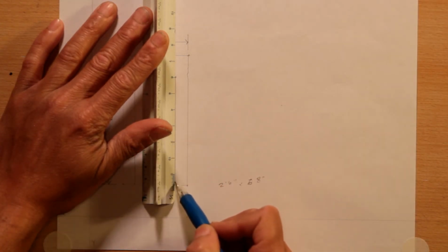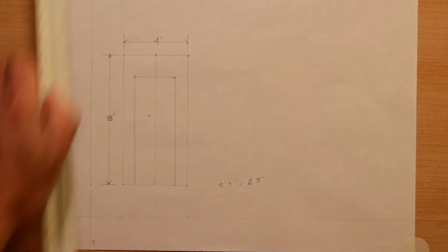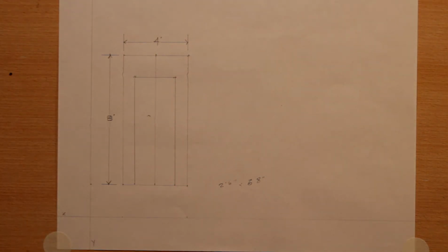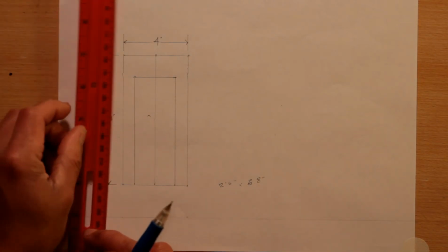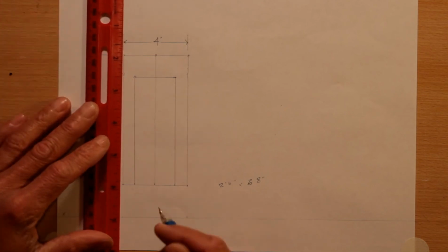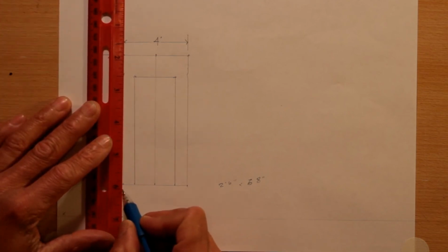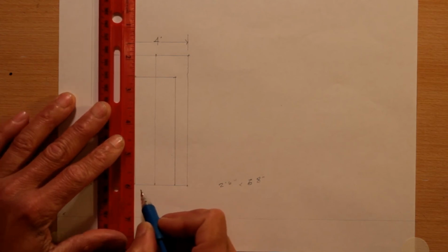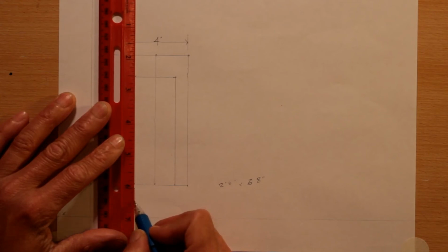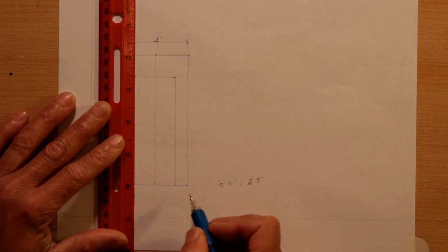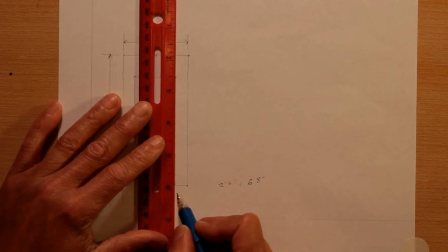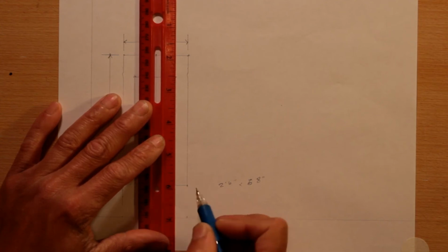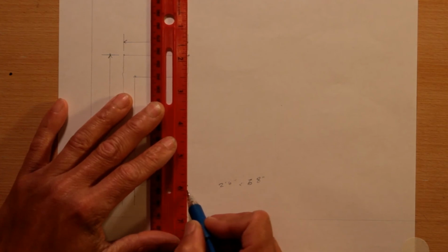Time for your extension and dimension lines. You will draw 4 vertical extension lines at the bottom of the flat, 1/2 inch long and 1/8 inch away from the bottom of the flat. These will line up with the outside edges of your flat and the interior edges of the doorway. Once your extension lines are done, add your dimension lines, scale measurements, and arrowheads.